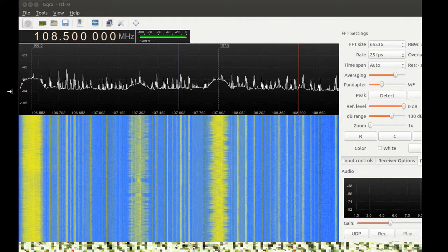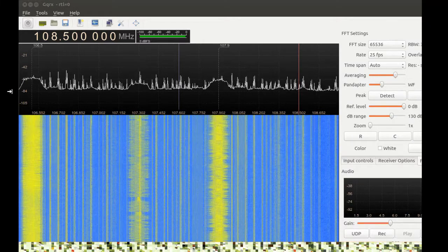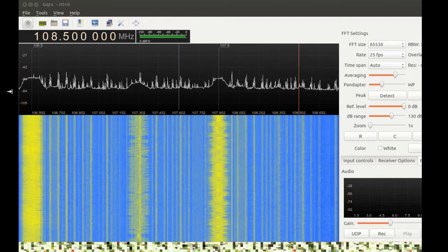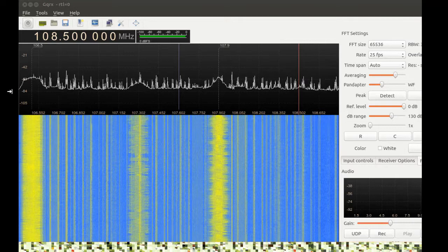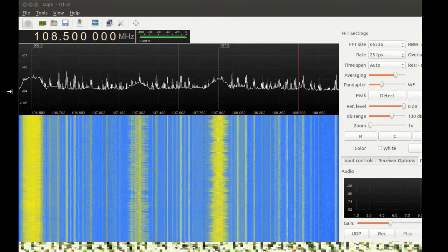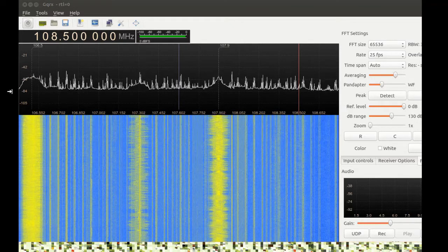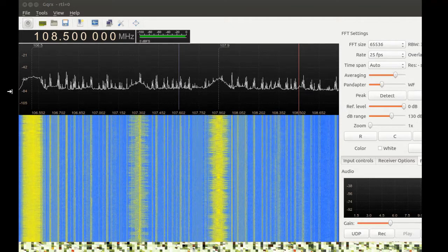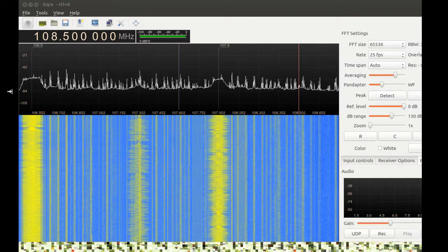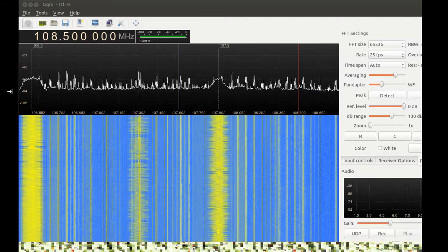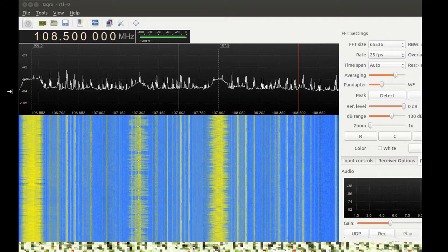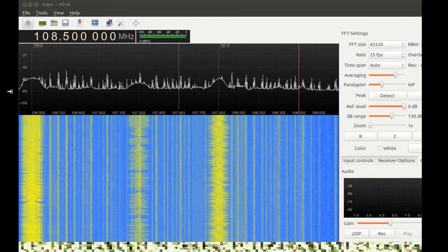I still have that same problem. So I think what you might be experiencing is... Is my antenna too small? Like I'm supposed to hear this, I'm assuming. Like I can barely hear. So go to your receive options. Squelch is good. Oh, see how it says mode narrow FM? Yeah. Change that to wideband FM. Wideband FM stereo specifically for these. And zoom way out, because...